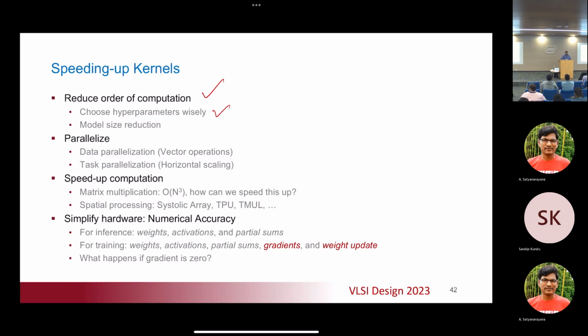So, for example, the latest thing that Intel is doing in Sapphire Rapids is they have a multiplication unit for acceleration, which can take a vector which is 16 by 64 and multiply them all in one shot. And so that's AMX. It's a tremendous amount of hardware, a tremendous amount of power, but it speeds things up. In the case of NVIDIA, they're doing similar things.